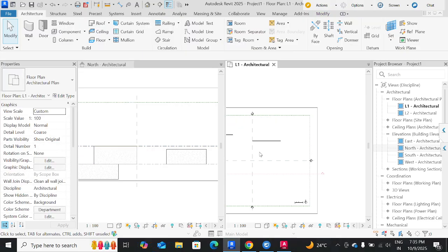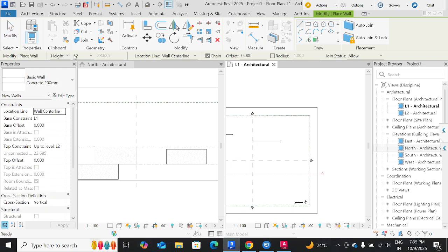One more thing I want to say to you is that Revit is a parametric software. So it is more related to the parameters, that is these properties, it will be linked to it always. So you have created the wall. When you give L2, it will give the limit. According to the limit, this height will be limited. If you change this one, it will automatically change.